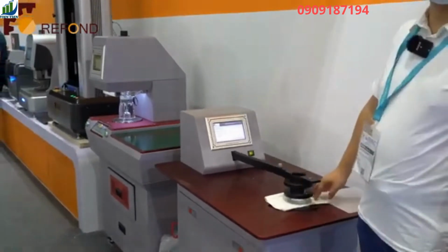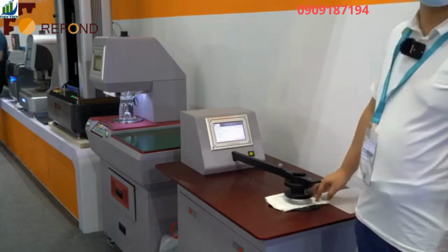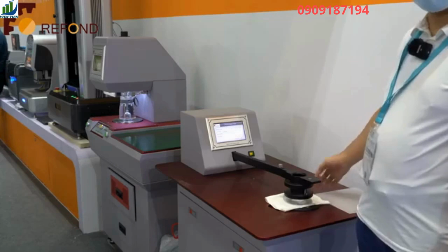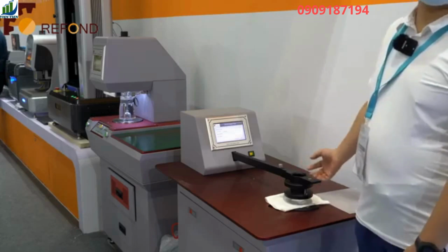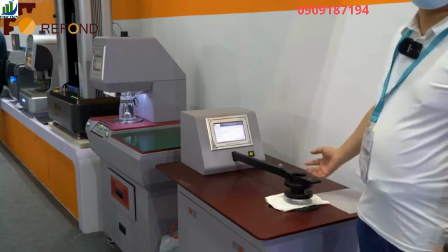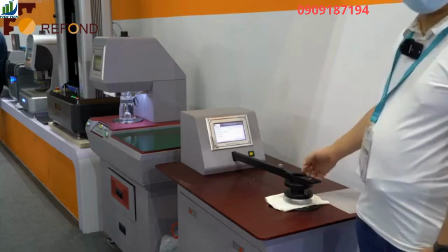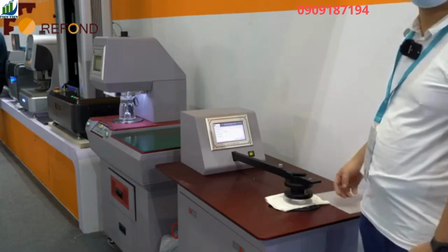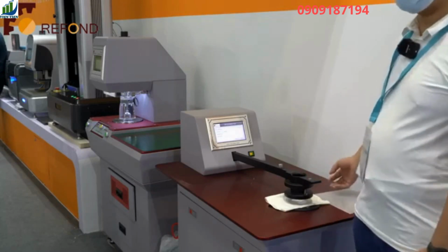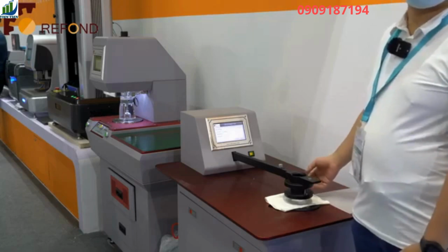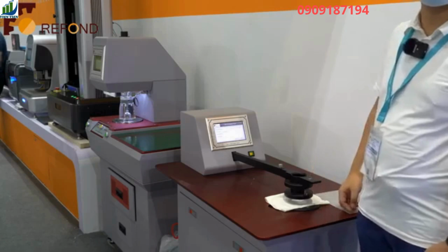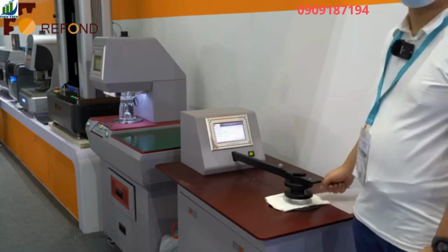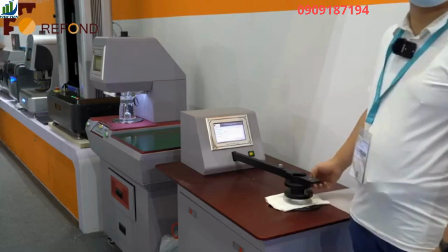The most important innovation for our new machine is that you can use an external calibrated airflow sensor or an airflow meter to calibrate the airflow for this machine. This produces better traceability than the traditional method of calibrating. The traditional method requires a different set of plates, which is labor intensive, and it cannot provide a lot of traceability. Now we can use flow rate meters to calibrate this machine.